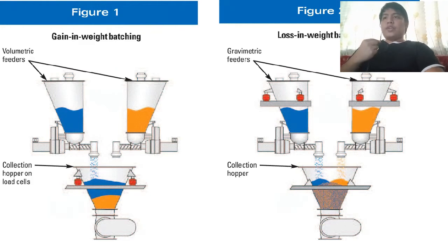The user can utilize a computer and a load cell that continuously records the weight of the feeder and its contents. The user can just input the given dispensing rate, and the computer automatically calculates the rate and begins the releasing process.